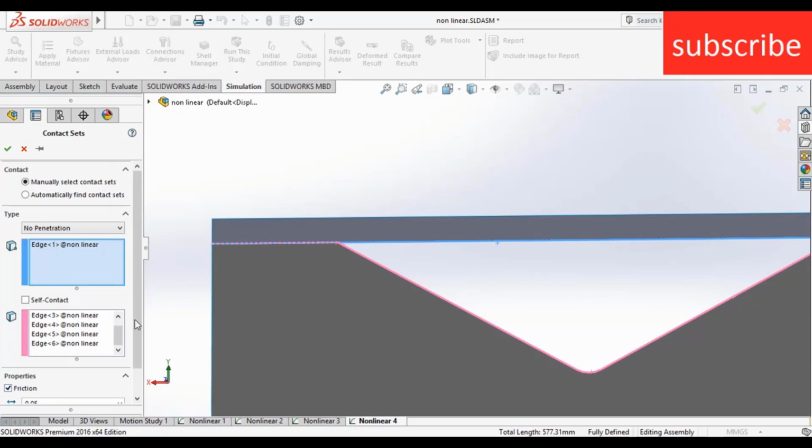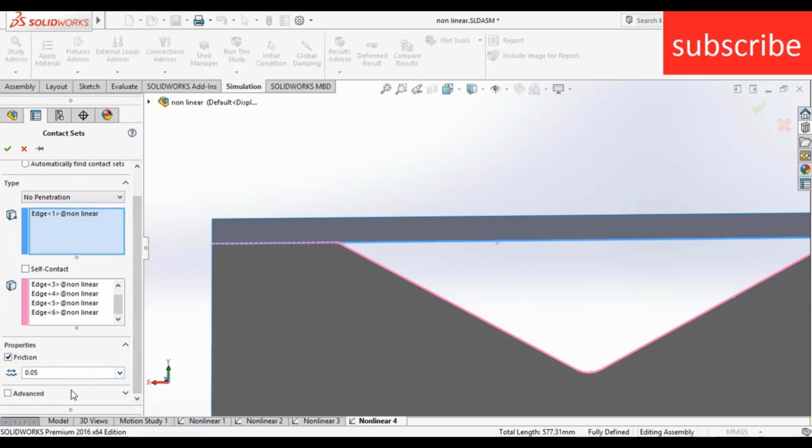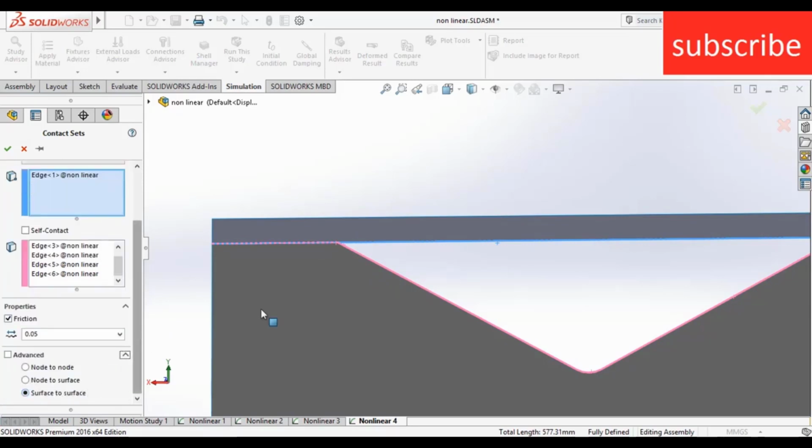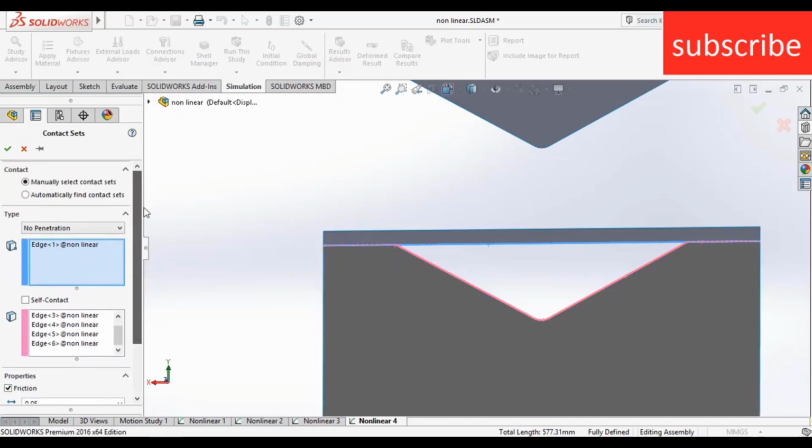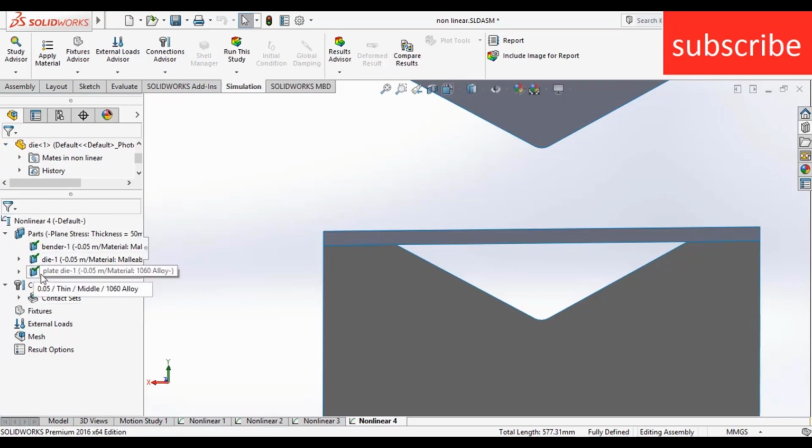Make sure you click on friction. Without friction, your simulation is not up to the mark, and you know, whenever you do deforming, friction plays an important role. Without friction, you can't deform anything. And make sure you select advanced and surface to surface, because the contact is surface to surface when our deformation is going to happen, so that there will be no penetration. Click OK. Now right click on it, click on contact set.